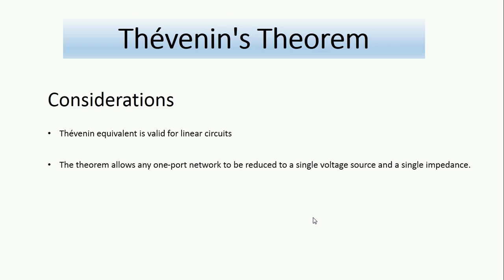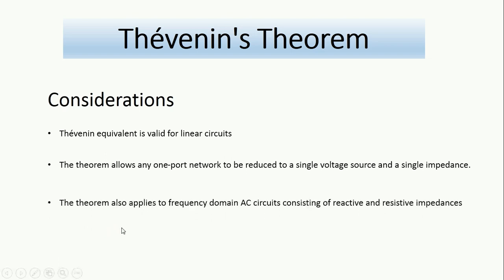The next thing is actually a question of whether this Thevenin theorem would also apply to AC circuits or not. Yes, of course it applies to AC circuits as long as they are linear circuits. Capacitors and inductors are also considered linear elements, so we can consider this a point of application for this theorem. For nonlinear elements like diodes and semiconductors, we cannot include them.